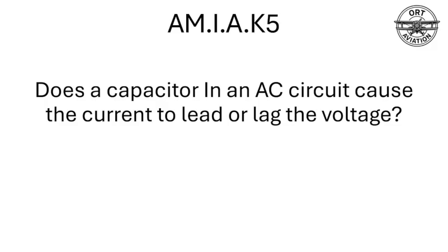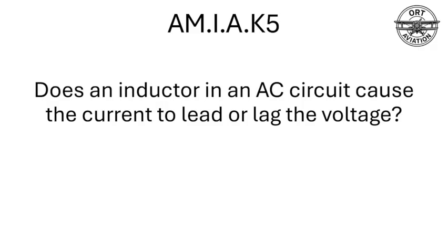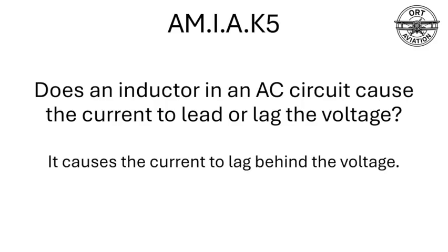Does a capacitor in an AC circuit cause the current to lead or lag the voltage? It causes the current to lead the voltage. Does an inductor in an AC circuit cause the current to lead or lag the voltage? It causes the current to lag behind the voltage.